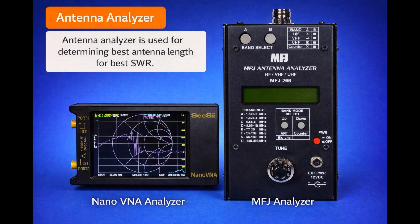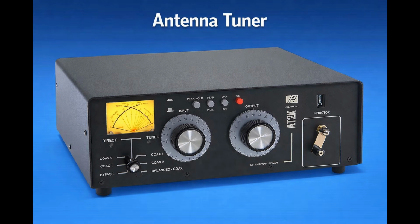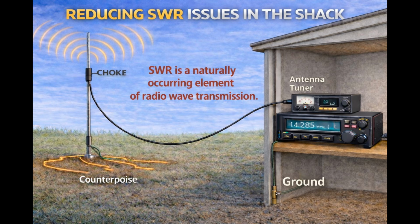We measure SWR using an SWR meter when constructing and installing an antenna. Also on high frequency, we use an antenna tuner placed in the feed line between the radio and antenna, or with the built-in SWR meter found in many modern radios. These tools compare forward power and reflected power and display the ratio. This gives us a quick and easy way to check that our antenna system is operating in a safe, efficient range, so our signal gets out cleanly and our equipment stays protected.